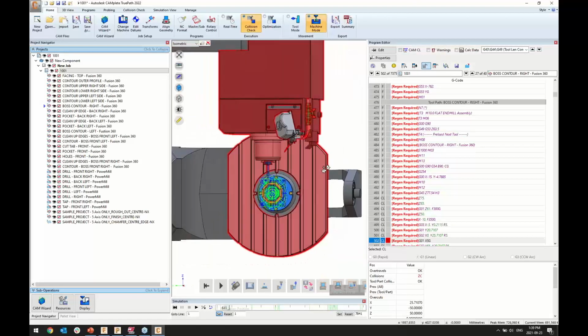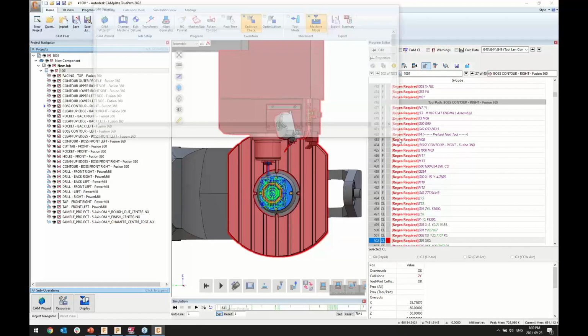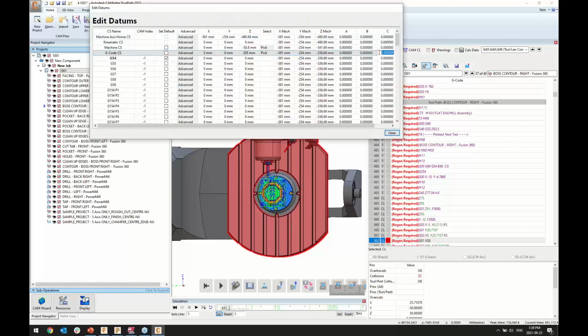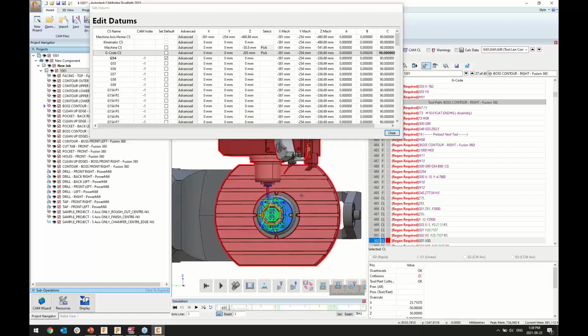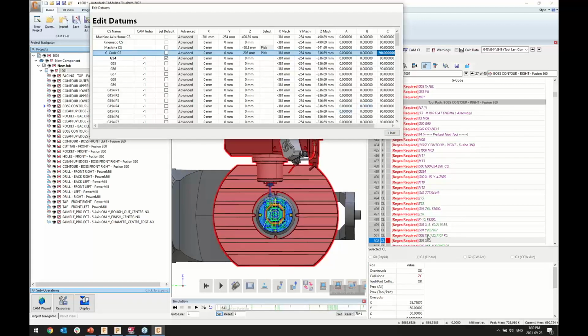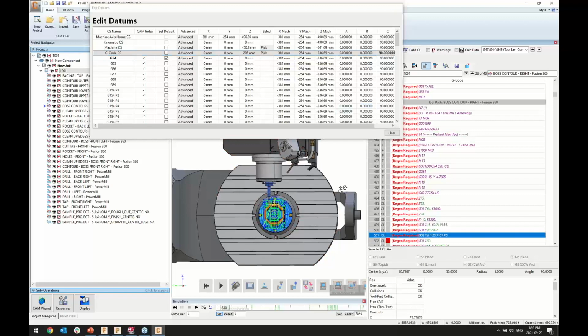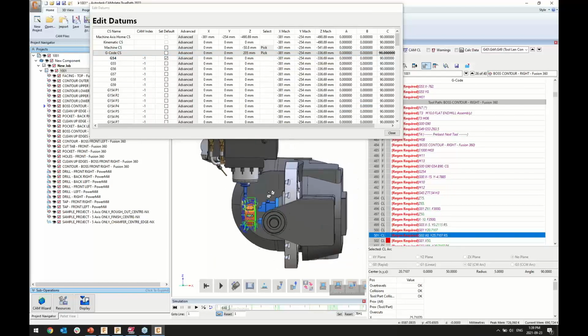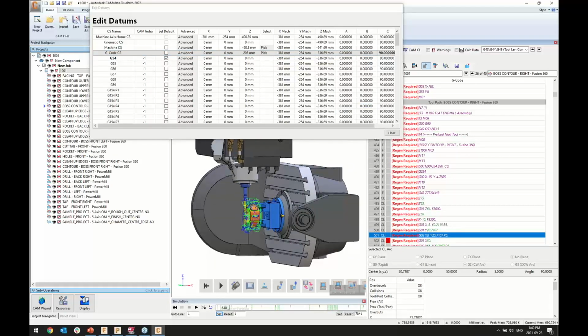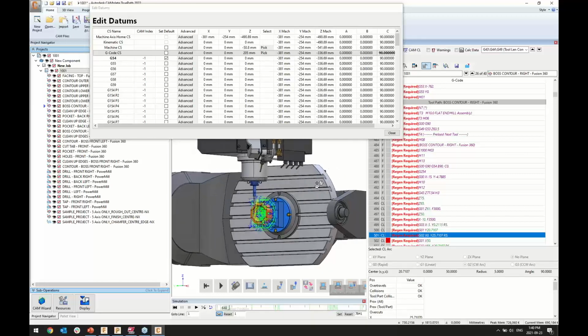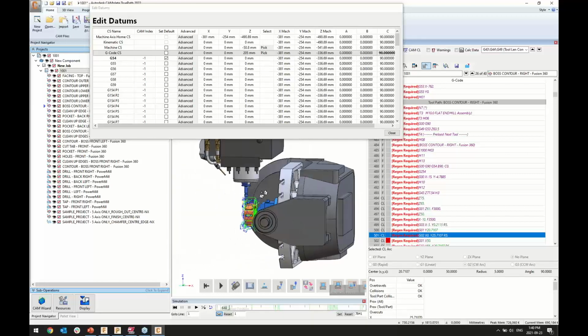But before I quickly jump into the code regeneration, I wanted to look at the scenario of what would happen if I just rotated my entire part 90 degrees when I go to clamp it. And now we can very clearly see that introducing that 90-degree rotation on the setup, simply rotating the part when it gets clamped on the table, would very easily solve that collision.